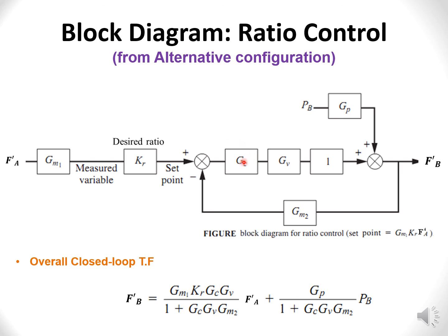The controller is still the conventional controller, like Cascade. The controllers are all still conventional. They are not advanced controllers. You don't need them also. You just need the conventional PI, PID, but just the slight loop, because based on the definition, again, look back at the definition, any loop that is different or any controller that is different, either one is called advanced control.